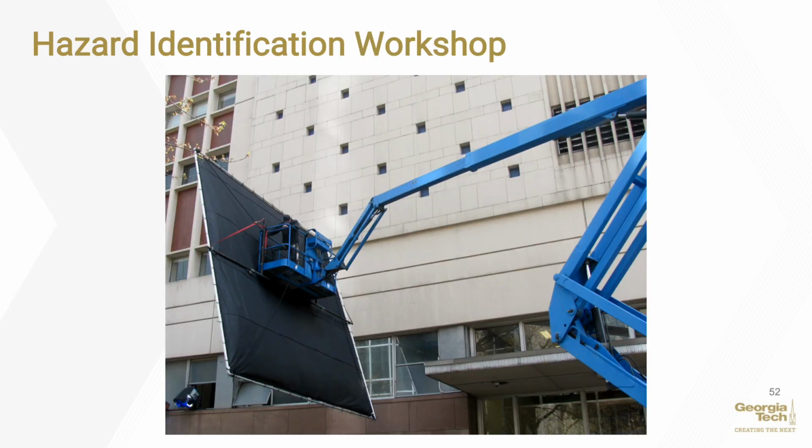What are some hazards associated with the picture? Fall hazards. Workers in the lift must be equipped with personal fall arrest systems. Weather, wind, load of equipment in the lift. Did you find any others?